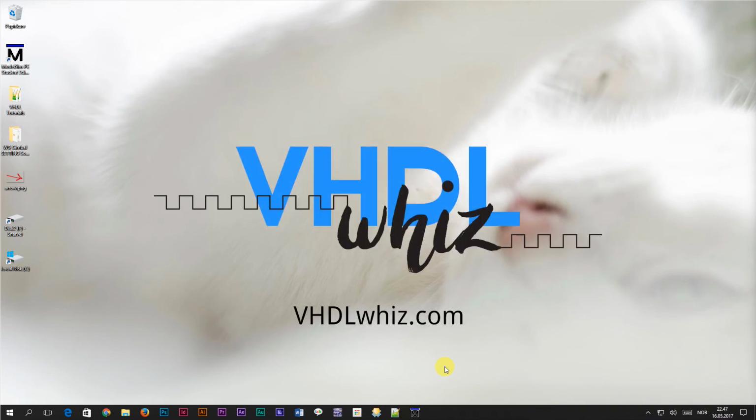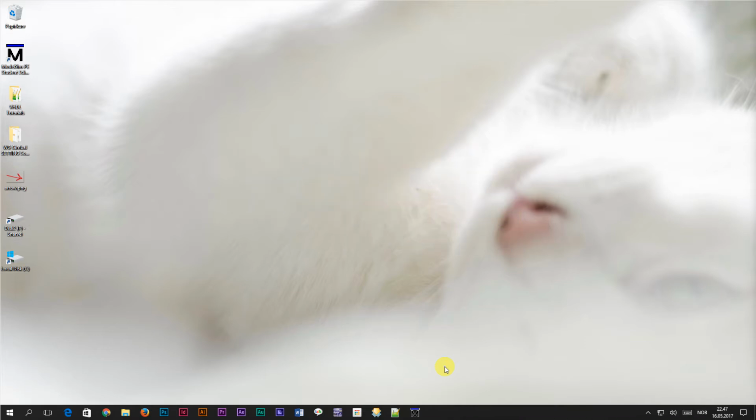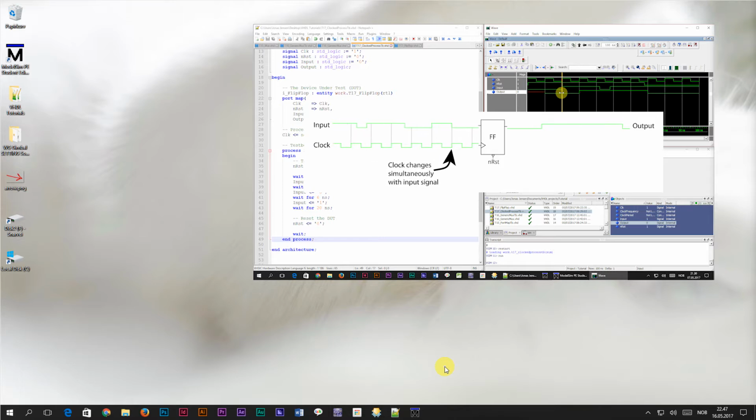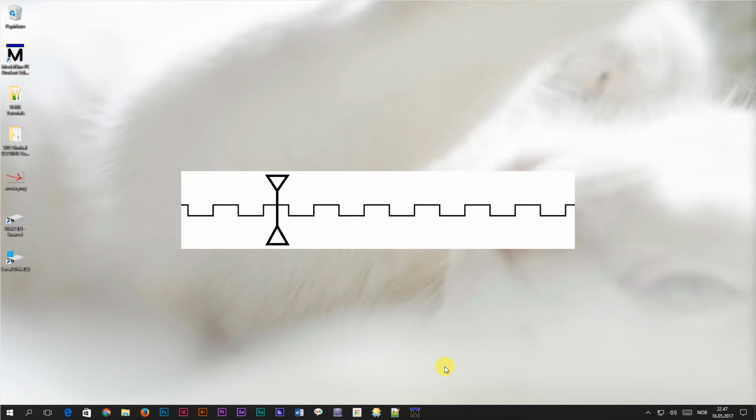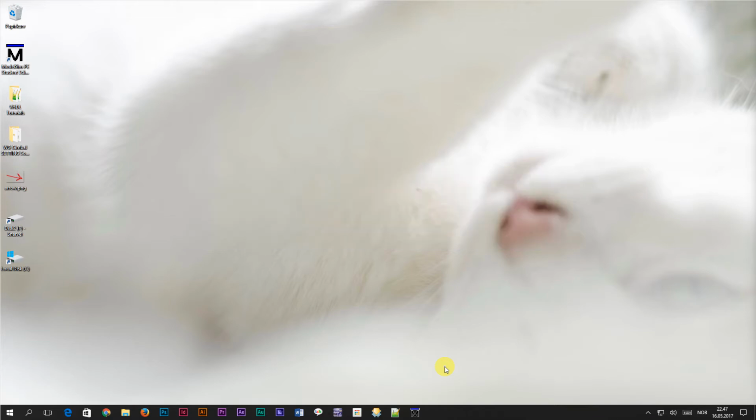In this video, we are going to learn how to create a finite-state machine in VHDL. We learned how to create a clocked process back in tutorial number 17, and in the previous tutorial, we worked on a timer module which used clocked logic. In clocked logic, or sequential logic as it's sometimes called, everything happens in time steps. Everything happens in sync with the clock signal on the rising edge of the clock. This makes it a bit easier for us to develop complex logic.